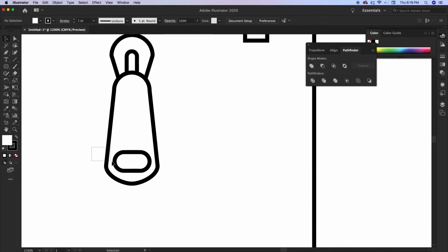Either you can just drag and create that box, and wherever the box is hitting, those are going to be selected together. You can do it this way, or you can just click on one and press Shift to do multiple selections. So again, we're capturing another set which is called selections. Here you do multiple selections by clicking on one of multiple objects while pressing the Shift key. If you don't use the Shift key and you just click on one, and then click on the second one, you lose the first one.